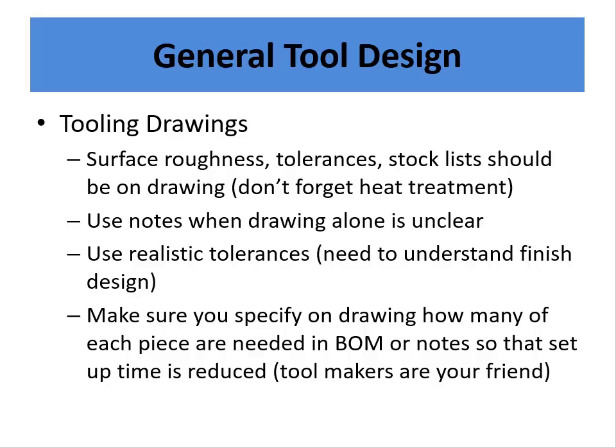Probably if you're doing the drawings and the design, you're probably not also making your tools. Someone else is probably making them for you. Remember, they're your friend. They're there to make the parts, and it's really easy to leave out information or overlook things and cause issues there. So the more clear information you have in a way that people are used to seeing, the better off you are. And that's just a general rule I would adhere to.